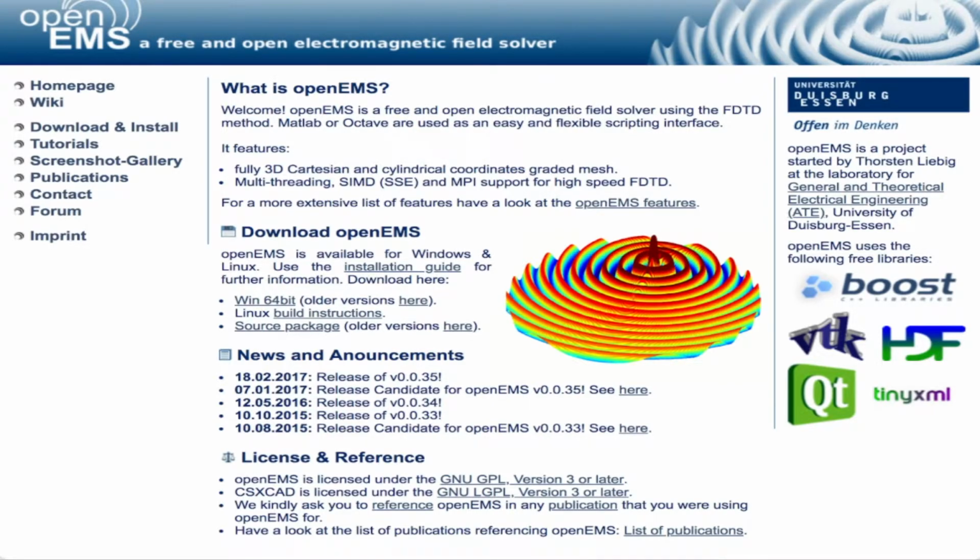There are various steps associated with the simulation process. First of all, the parameters that define the type of simulation, such as the boundary conditions and the number of simulated steps, are saved in the FDTD object, and the parameters for the geometry are saved in the CSX CAD object. Secondly, the properties of the structure being simulated must be defined. These properties include the physical properties such as materials used and non-physical properties such as probes. The primitives take the non-physical properties of the scattering objects, field sources, and field dumps and assemble them as objects such as curves and polygons. These are then stored in the CSX CAD structure.